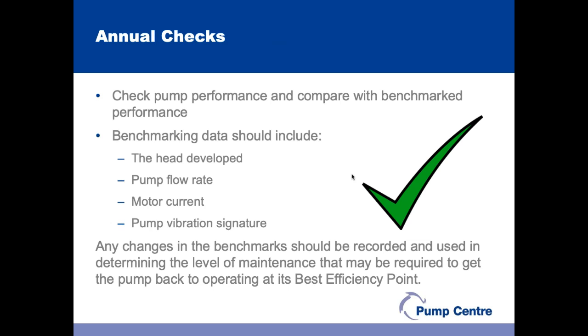And then what I'm suggesting on an annual basis is to go in, have a look at that data, do a comparison, and that may give an indication that it's time to carry out perhaps a minor overhaul, or perhaps to adjust some wearings, or whatever's necessary to try and get the pump back to operating at its best efficiency point. So certainly for larger pumps, a really useful activity.